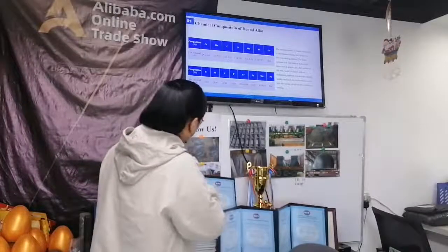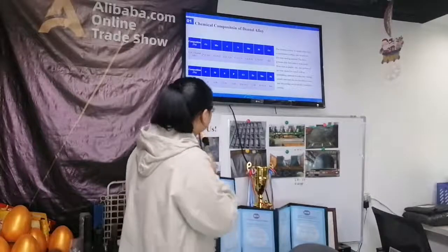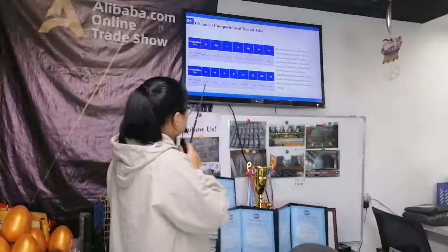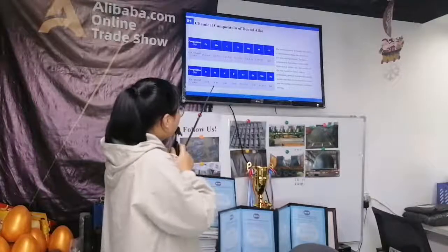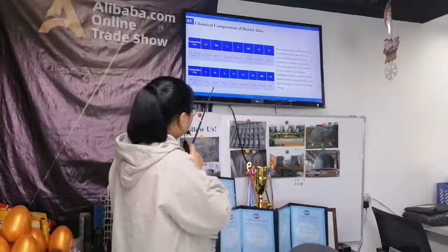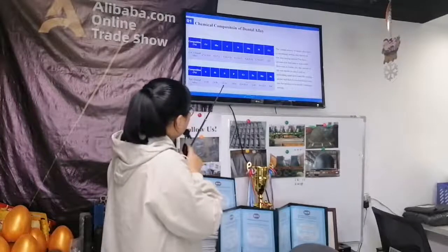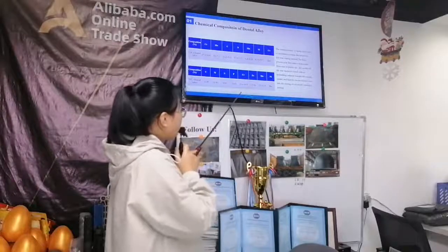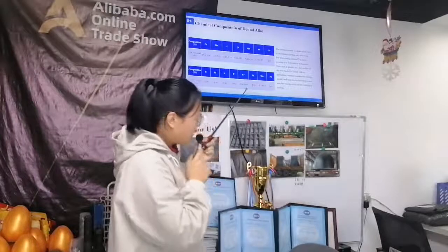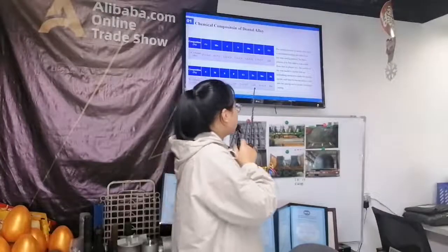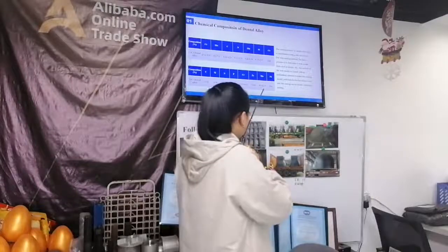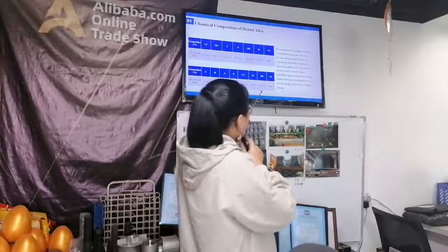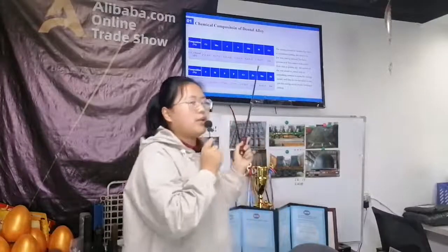This one is nickel chromium dental alloy. For carbon is less than 0.05%. For silicon is 1.5%. For chromium is 22.26%. For iron is less than 2.0%. For molybdenum is 9 to 11%, and the nickel is balanced.